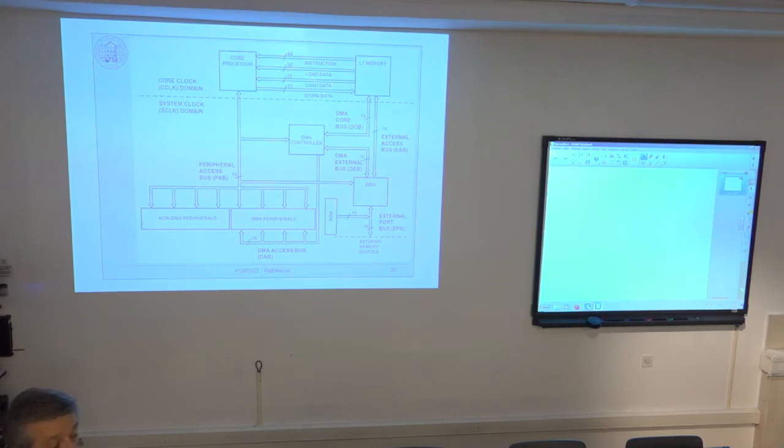So only when the whole block is loaded, for example, 128 data values in memory, would you activate the interrupt, and the processor would process the whole block immediately. So this is the way to increase the efficiency. The CPU core does not have to service each particular data sample coming to these high speed peripherals.